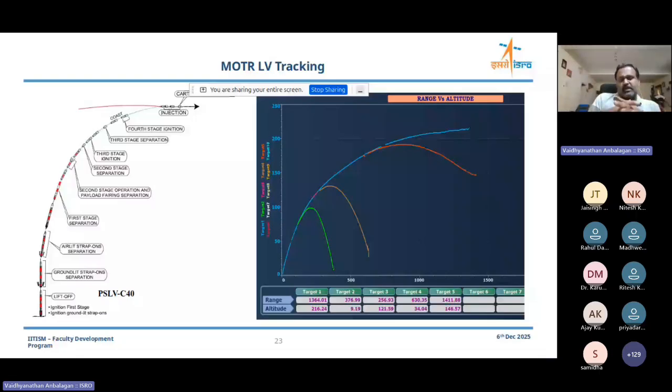But you have a mass of a satellite. So a 1 ton mass, say 2 ton mass satellite or a 4 ton mass satellite needs to be put into that orbit. So correspondingly, the launch vehicle guides and takes the satellite to a particular height. And once the particular velocity is achieved, we say that the injection parameters, the required velocity for the satellite is achieved. Now we can release the satellite. So what we call it as a satellite separation. So that decision is taken by the final stage on its own. Once the particular velocity is achieved, the satellite is put into the orbit.